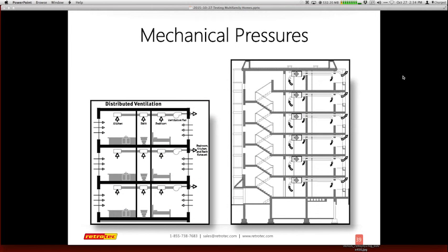These are some of the mechanical pressures that are happening. If you look at the illustration on the left, we're talking about the kitchen, bath, and bedroom. These are all my ventilation, an exhaust-only type of system. Sometimes this may be individual units, which I think most of these multifamily buildings are going to go back to, versus a single source throughout or units with their own ERV. The 62.2 rules are beginning to change, trying to isolate individual homes from commercial common areas. So you can see some of the plays in terms of the pressures you might be trying to evaluate as you're at that structure.